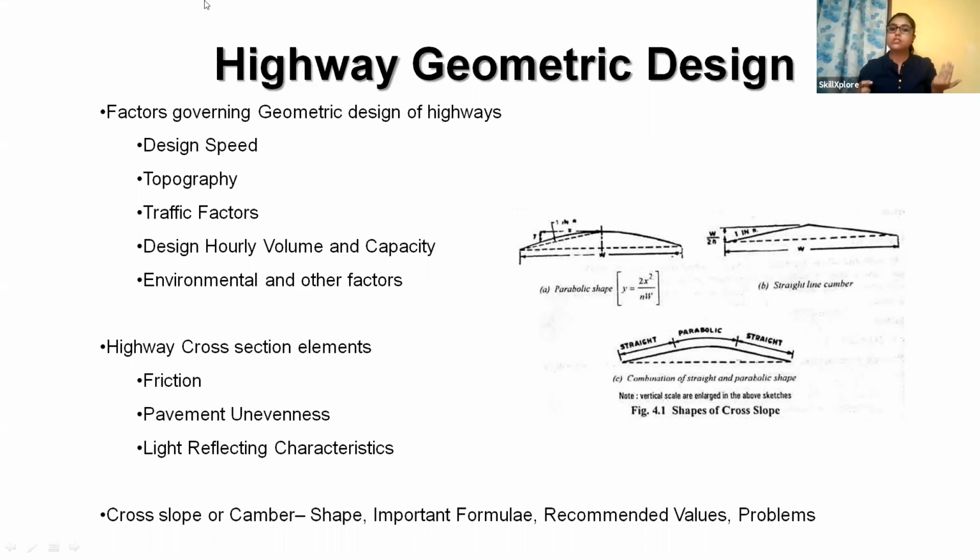So for the camber itself, in the first, Tresaguet construction, they considered the slope for only the surface layer. They didn't give the slope for the subsurface or the subgrade layer. In that case, they identified the problem that if we are not giving the slope for the subgrade layer, then that causes some problem. So step by step, they identified the concept of this camber right from the initial time itself. So from that, we can understand how important the camber is.